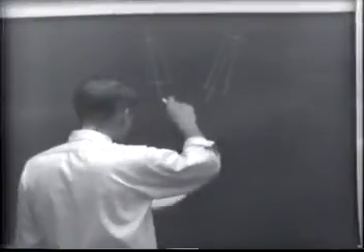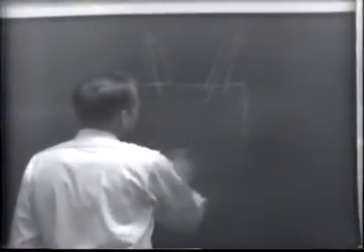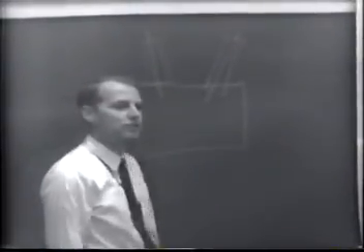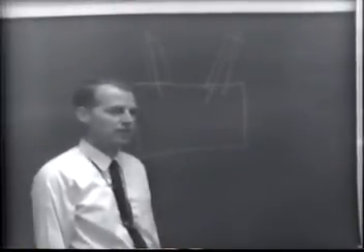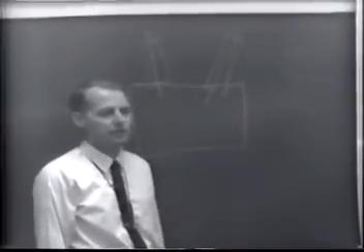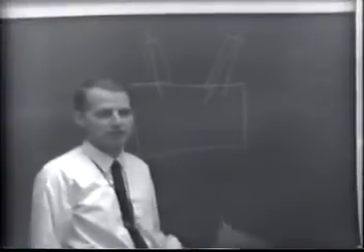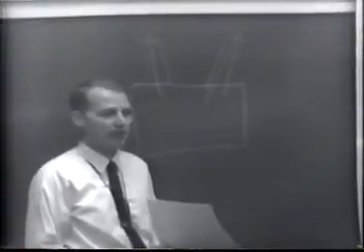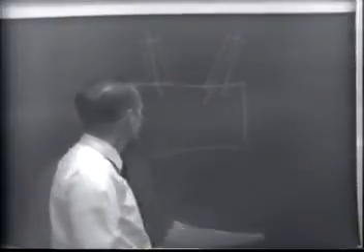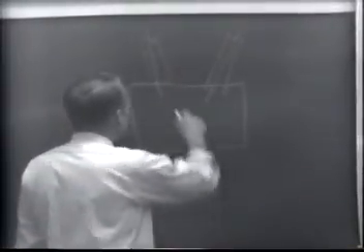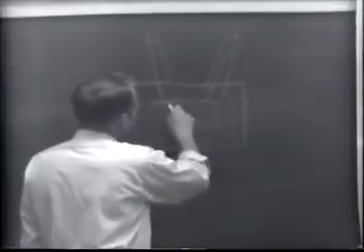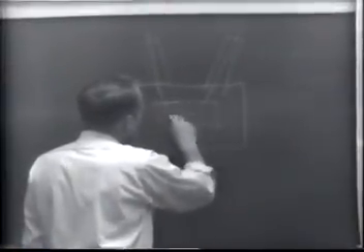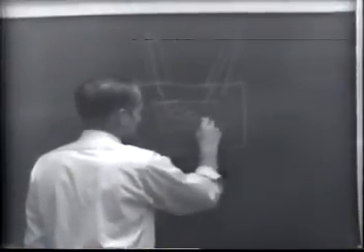We have to have some kind of an insulating structure to maintain the line to ground insulation at all times, and when the circuit breaker is in the open position, we have to have insulation for the full line voltage at all times. And we have to have basically an arc interruption mechanism.